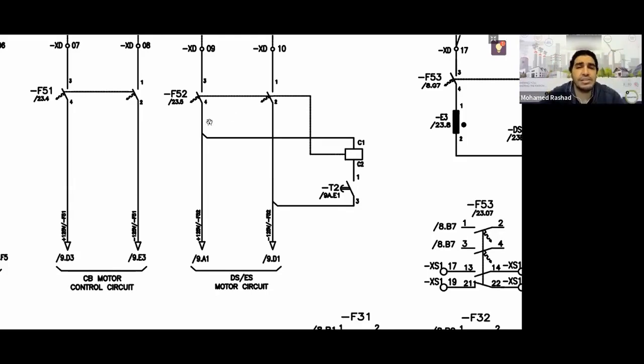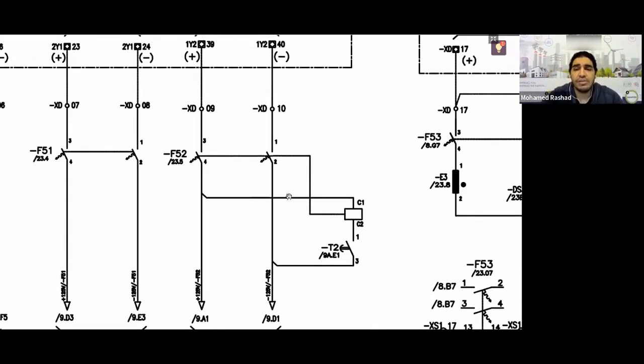What does it disconnect? The trip unit, which has terminals C1 and C2: C1 takes the positive from this rail here, and the other terminal takes the negative from the other rail. But this connection is interrupted by a switch. So as soon as you close the miniature circuit breaker, it receives the positive from above to get the negative. This happens when the timer finishes counting. As soon as the timer finishes counting, the negative comes directly to C2.